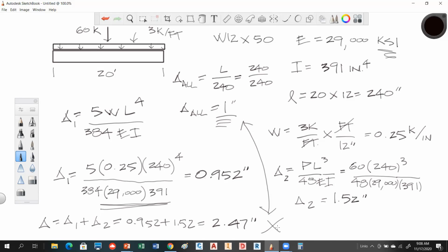So guys, if this is the allowable for that situation, and this is what we're coming up with, what do we do here to fix this? How can we get that number down? Taking the beam. Yes. In other words, increase what? The moment of inertia, right? Yeah, because if you're steel and you're going to have to use steel, then you're not going to change this number much.